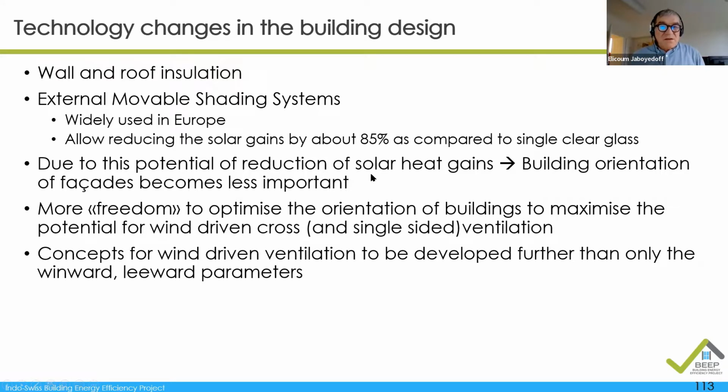Which also means that, to some extent, there is more freedom to look at building orientation, because the orientation of facades becomes less important for heat gains as compared to old non-insulated buildings. And it gives more freedom to optimize the orientation of the building to maximize the potential of wind-driven cross and also single-sided ventilation.